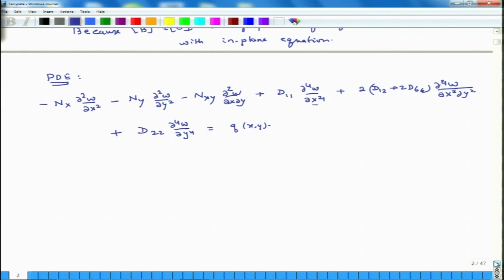Now, in our equation, q is equal to 0, and because the plate is nice rectangular symmetric lamination, because of the geometry and all that, Nx inside the plate is also 0, Ny is also 0, and Nxy is the same as S, because the plate is rectangular and it is uniformly loaded on the external edges by uniformly applied Nxy whose value is S. So, at every point we will assume that it is the same thing.